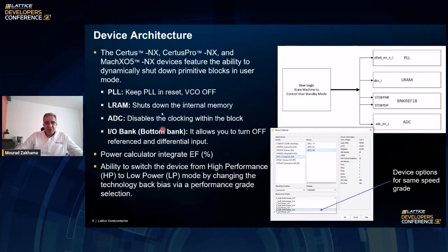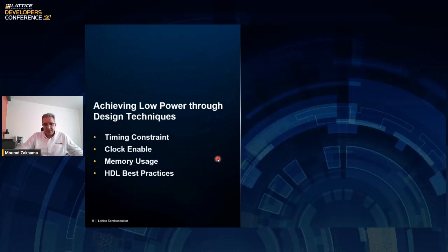Obviously, when you use any of these techniques or features in the power calculator, as we've seen in the previous session, there is an EF factor that allows you to provide a percentage of time that these blocks are active, so it accurately represents the power consumption of your device.